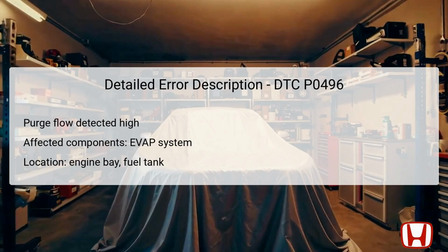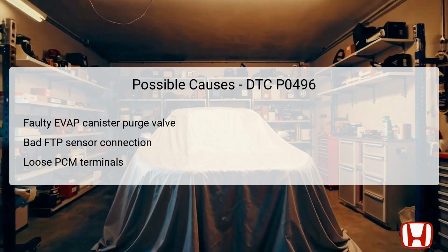Moreover, the PCM, or powertrain control module, plays a vital role as it processes signals from various sensors and commands the purge valve accordingly. Diagnosing this error requires identifying whether the system's components are functioning correctly and if any electrical connections are compromised. Several potential causes can lead to the